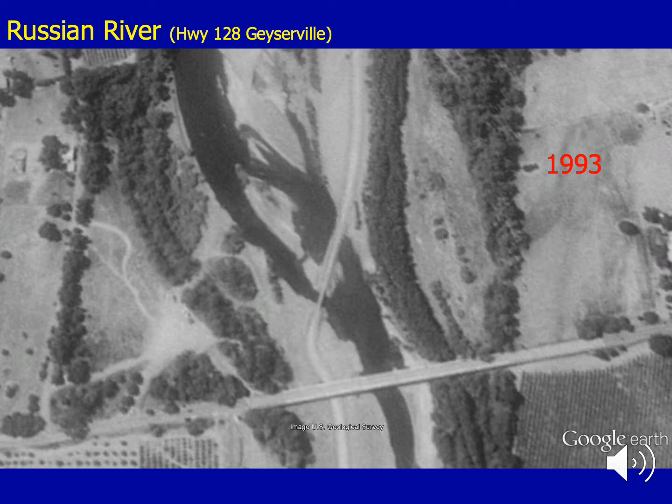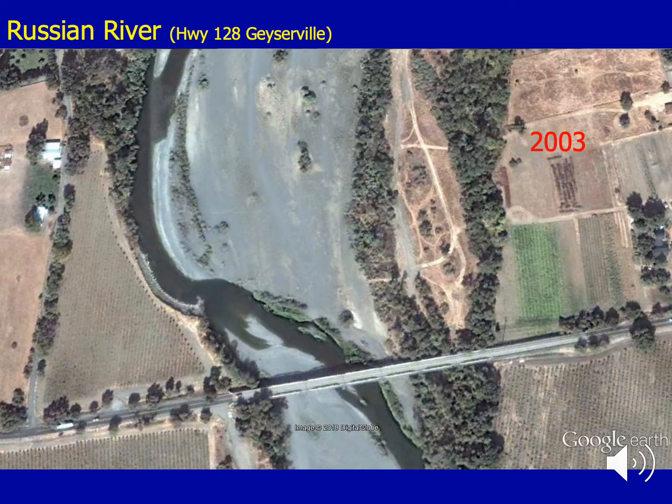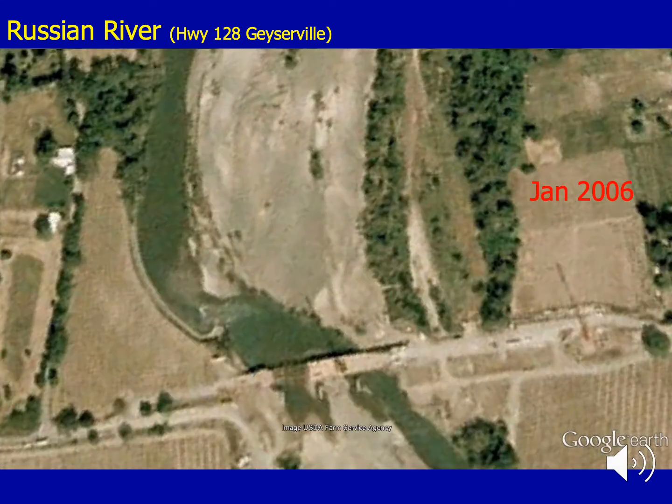And right away you can see the bridge abutments are inside the meander scrolls of this channel. And the other thing that's pretty obvious is the bridge is kind of skewed to the primary valley axis of the Russian River here. This end's kicked up. By 2003, there's quite a bit of right bank erosion happening here. The vineyard's starting to go away.